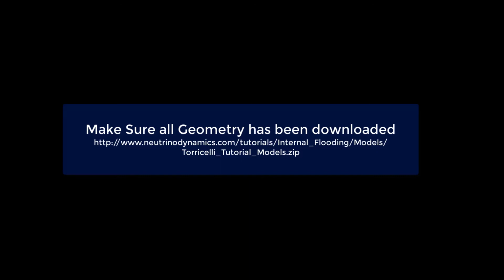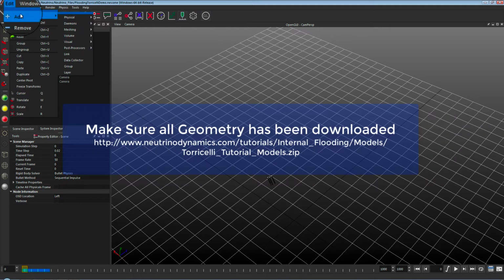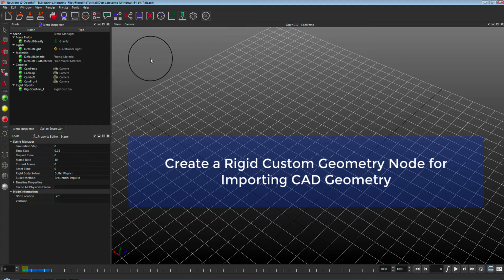I will pause here for a few seconds for you to make a note of this, or you can click on the link. Okay, let's go ahead. Let's now create some rigid geometry objects for boundaries in Neutrino. You can create it from the Edit menu to the Rigid and Rigid Custom, or you can use it from the Scene Builder, and we'll show that later.